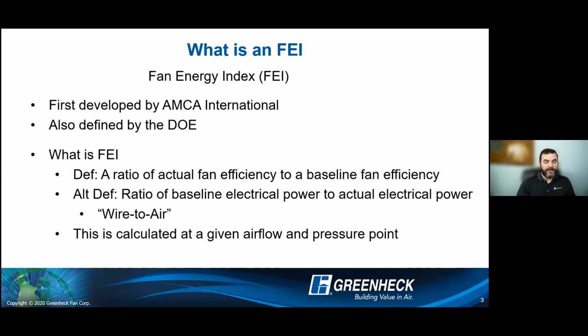Now, the last line here on the slide is actually a key statement. We are not just looking at peak efficiency for one fan, because even though a fan could have a great peak efficiency, where you're using it, or at what performance point you are using that fan, it could shift drastically how efficient that fan actually is. So one of the biggest benefits to an FEI is the fact that it is calculated at a given airflow and pressure point, at that performance point.